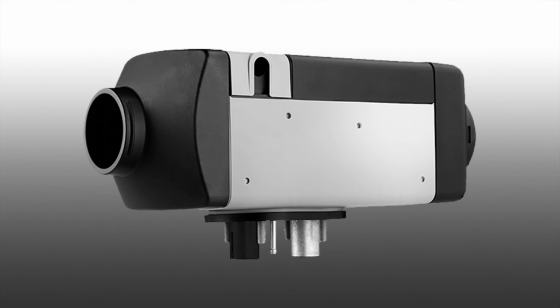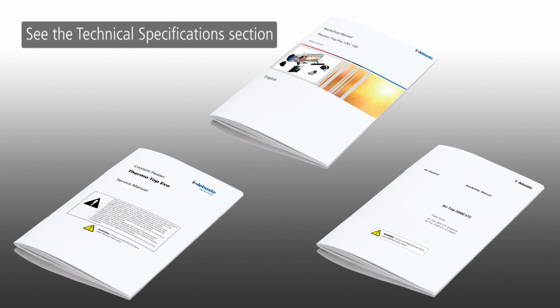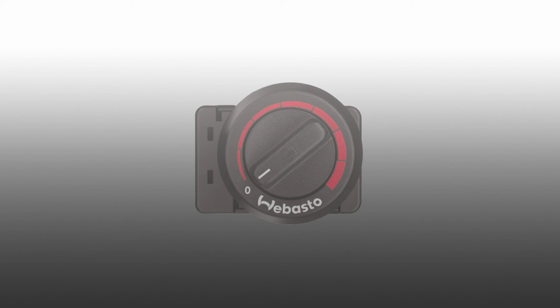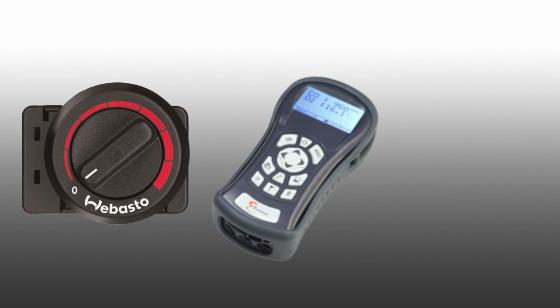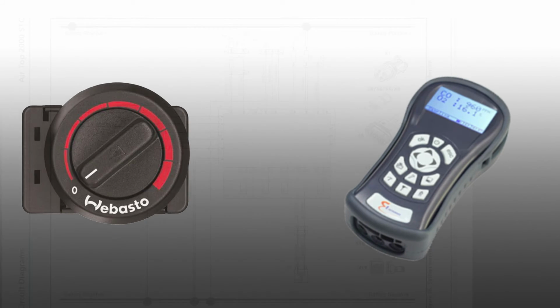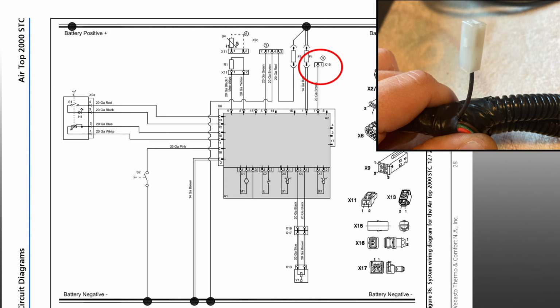This procedure covers the air-top line of heaters and is offered as an example. Please consult the service manual for the model of heater you're working on for the specifics, as well as the target CO2 specification. The rheostat control dial can be used in conjunction with a calibrated exhaust gas analyzer to adjust the CO2 output. With the control dial in the off position, ground the brown wire on the X15 connector.